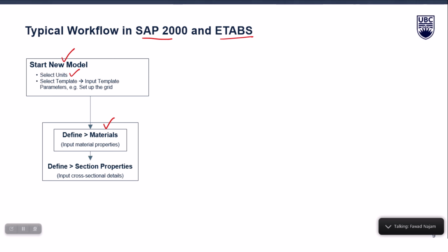And why I enclosed the material property also in that, because while you will be defining cross sectional shape, you will be associating a material also with that, right. So, you will be defining saying that okay, my beam is 0.5 meter by 0.5 meter, but at the same time you have to select which material it is made of. So, the material which you defined earlier needs to be linked to that cross sectional property.